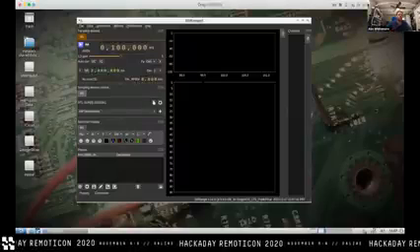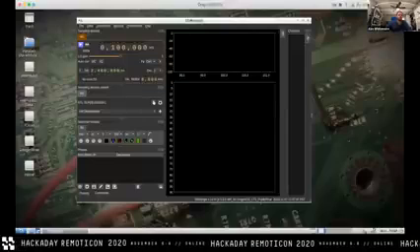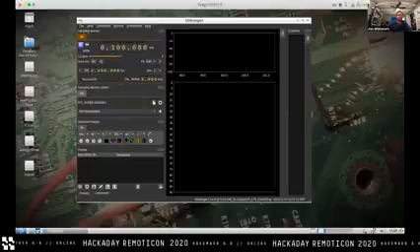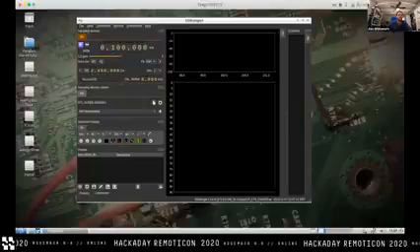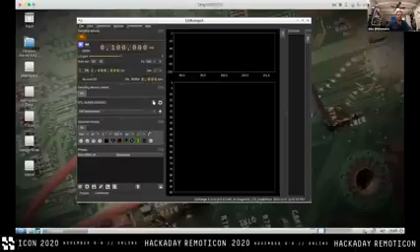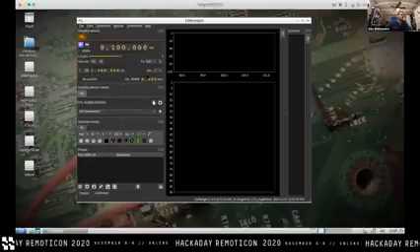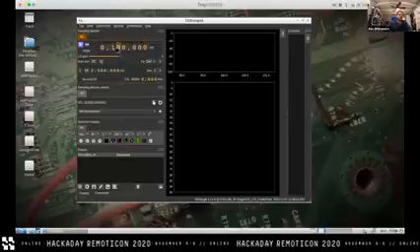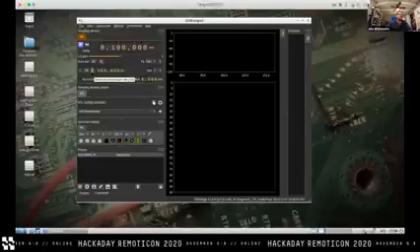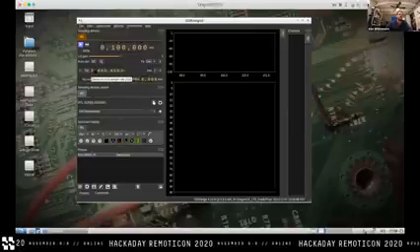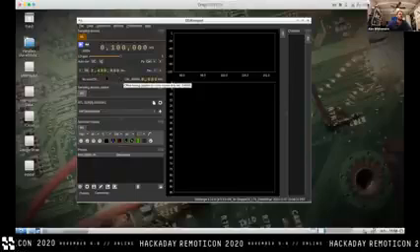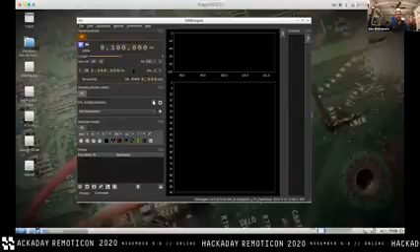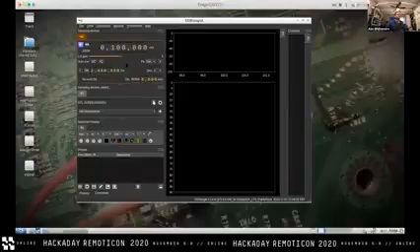Recall that this is not operating as a swept spectrum analyzer. This doesn't have anything like that. So the sample rate affects the maximum bandwidth span, where previously I was setting that span to 100 megahertz and setting the center frequency at 50 megahertz over on the RSA. Right now, I've set the center frequency at 100 megahertz. The span is set by the sample rate. So we've just got 2.4 megasamples a second, which is a 2.4 megahertz bandwidth. It's I and Q, so Nyquist is satisfied.